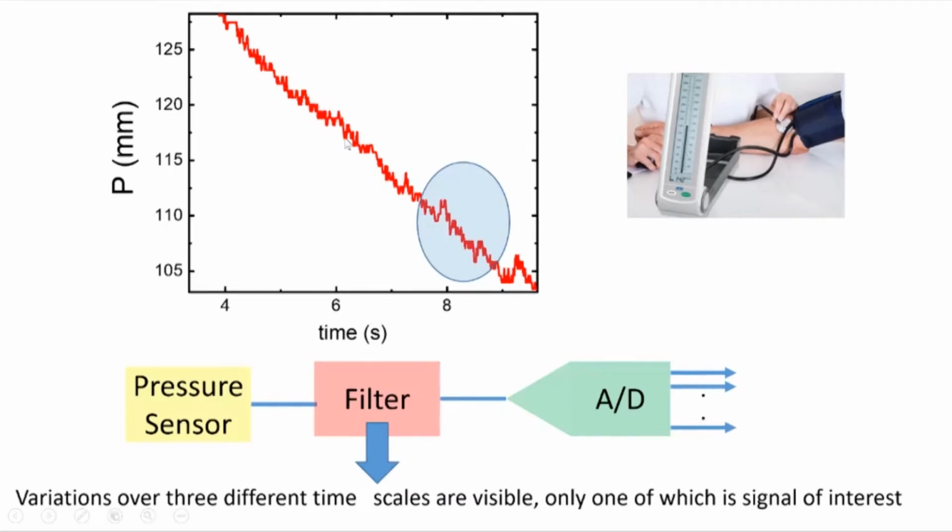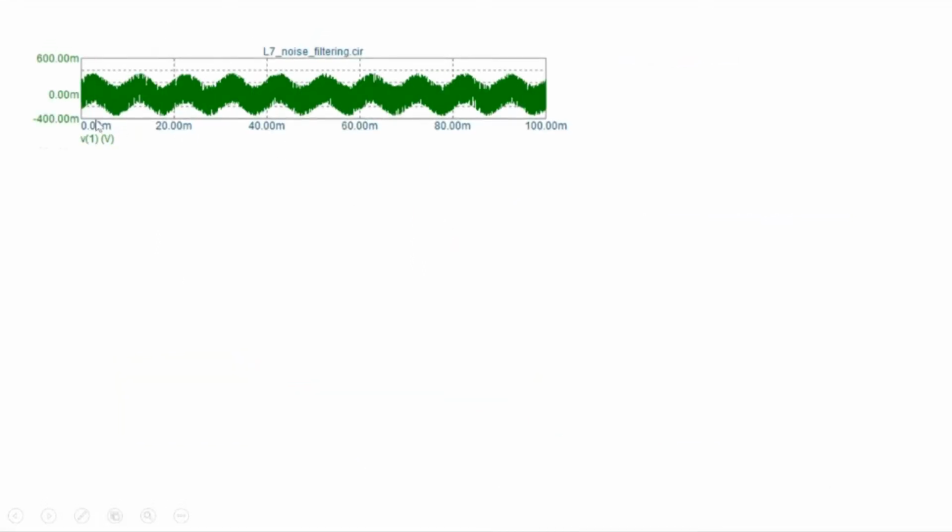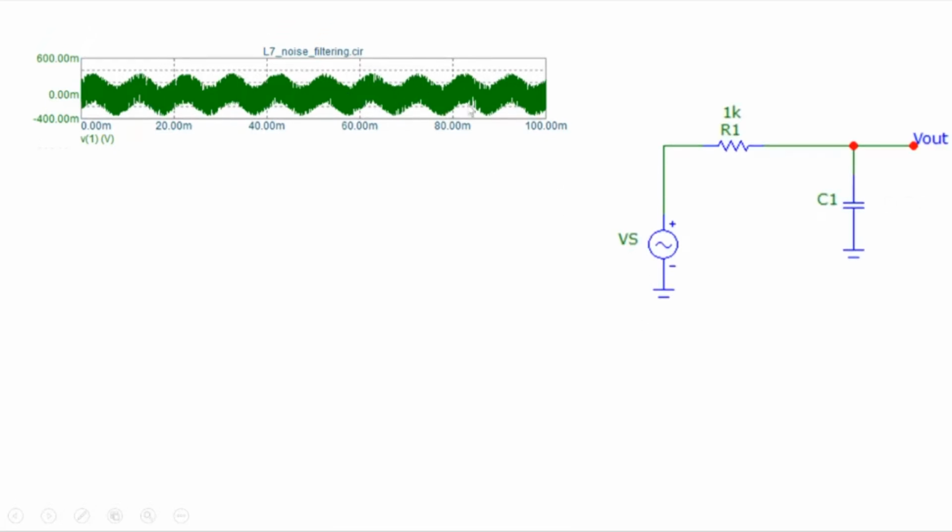Now, this noise filtering, this is a slightly complicated signal. I can illustrate noise filtering through a simple example, through simulation. Let's say you have a noisy signal here. You can see these very sharp variations around noise, but you can also see that there is some periodic signal. There's a sinusoid here. So it's a periodic signal immersed in noise.